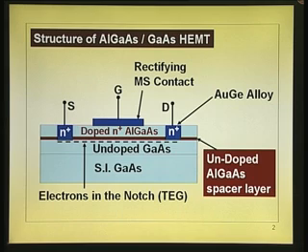If you just take only the top layer, N plus source contact, N plus drain contact, then doped aluminum gallium arsenide, that is the equivalent of the MESFET. But we disable the MESFET here by putting a gate on this, which actually depletes the entire layer. Okay. So, when you deplete that, and also when you have this doped aluminum gallium arsenide on gallium arsenide, you have got a two-dimensional electron gas here. So, it is these electrons which we are actually using for current transport.